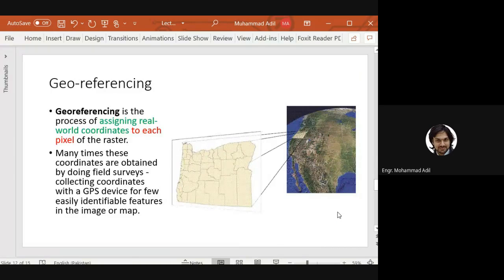So this is what is called georeferencing. Whenever we will be drawing our maps, we will georeference that map with 2 or more points, or with 1 point and north and scale of that map. Then we'll say we have done the georeferencing, and it is very important because it will be used to locate other places we haven't visited, but we have drawn them on the map. We can locate them, we can get so much information, their distance, their areas from the map, unless or until it is georeferenced. Any question about georeferencing?